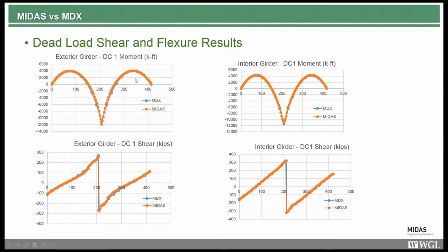Going back to the importance of the construction sequence and the deck pouring sequence, first, these deflection results look a little bit not what you would expect because they're not symmetrical while the structure is completely symmetrical. And this is entirely due to the deck pouring sequence. As you see, we poured the first span first in the previous model. So this is causing larger deflections when that first wet concrete is applied. And then as the section goes composite, we're seeing less deflection effects in the second pouring sequence.